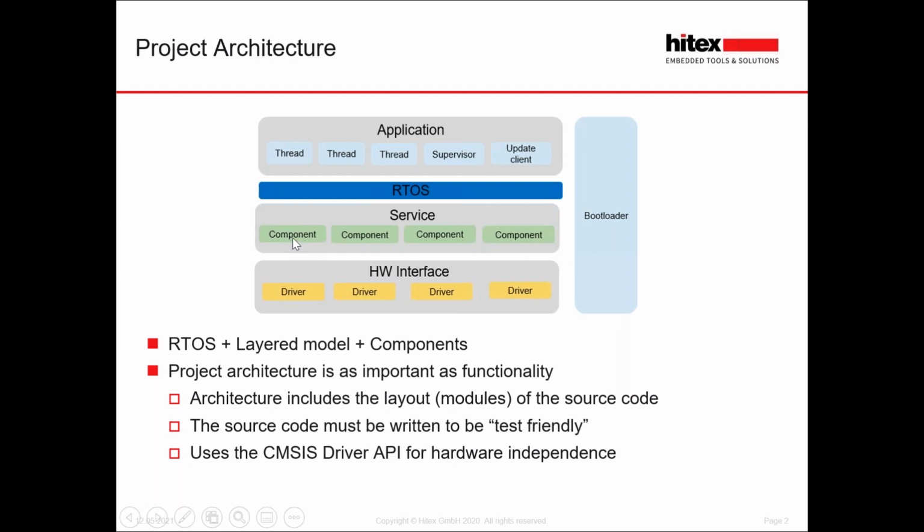And these components are isolated from the hardware through a lightweight driver layer that's based on the CMSIS driver specification. So what we have throughout our projects is a set of software components that provide the application functionality that are designed to be independent of both the thread code and the driver layer,